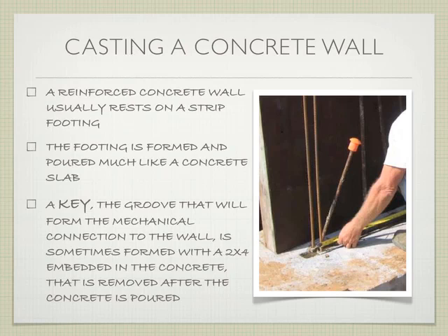And we talked a little bit about this a couple classes ago, about the challenges of having what's called a cold joint. A piece of concrete that's already cured, and then you're going to pour a wall on top of it, or continue a column in a separate lift. Somebody in the back asked a question about it. I don't remember who it was. So the same thing happens on a footing, where we poured this, it's cured, then we form up the wall. So we need a way of attaching these two pieces together. And so we do two things.